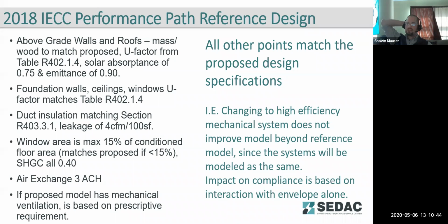We do have another question here about where do the 3 air changes per hour relative to other higher values we encounter. Where is it relative to diminishing returns? What does that 3 ACH mean as far as your compliance? Typically what we find in a lot of residential construction now that people are used to doing that air sealing, that 3 air changes per hour is usually beaten. It's uncommon now for most newer buildings, new residential buildings, to be above that 3 air changes per hour.